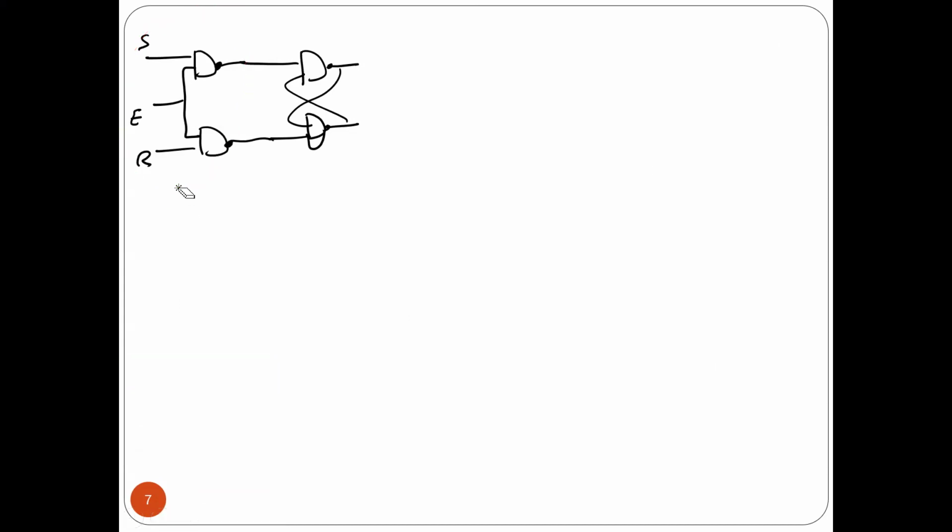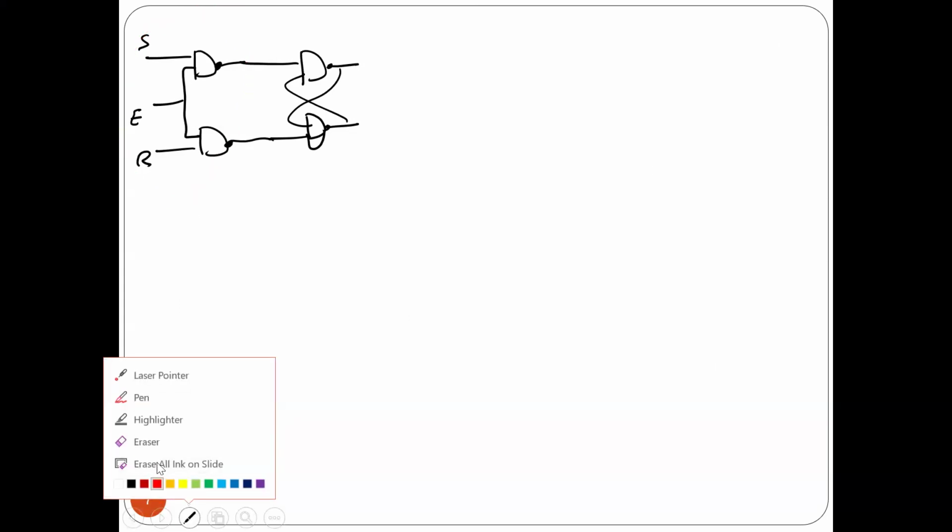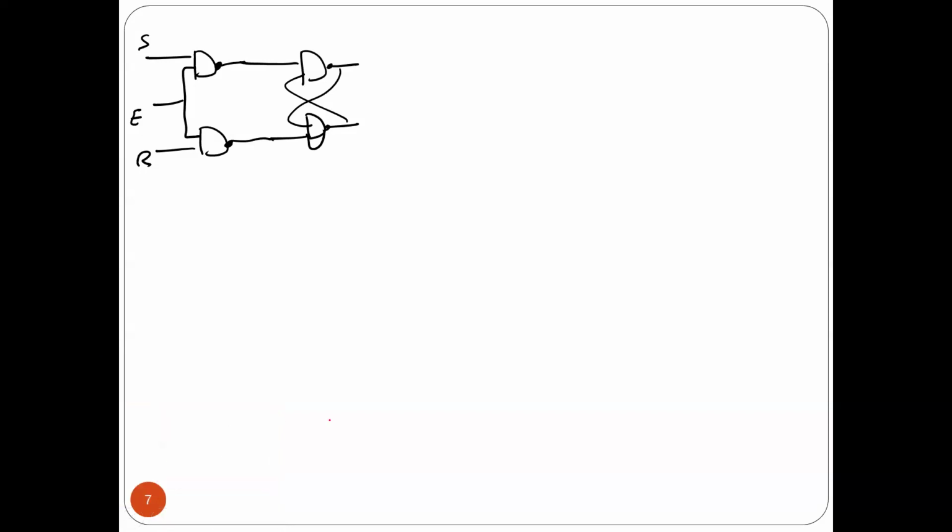As you know, in the case of NAND, if one input is 0, then regardless of the other input, the output is 1. Is that okay? That is why, if the enable is 0, this is the enable, to enable or disable. You already had this concept before, the idea of having an enable in any device. We like to have something like that in logic circuits to have control over the circuits. You can turn it on or turn it off, okay?